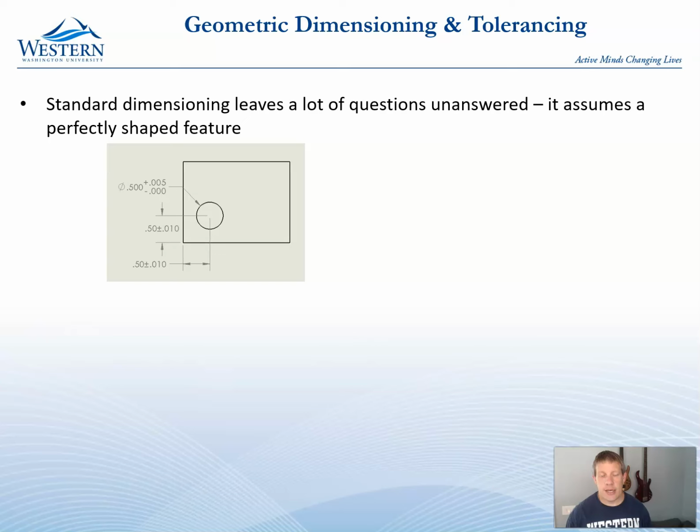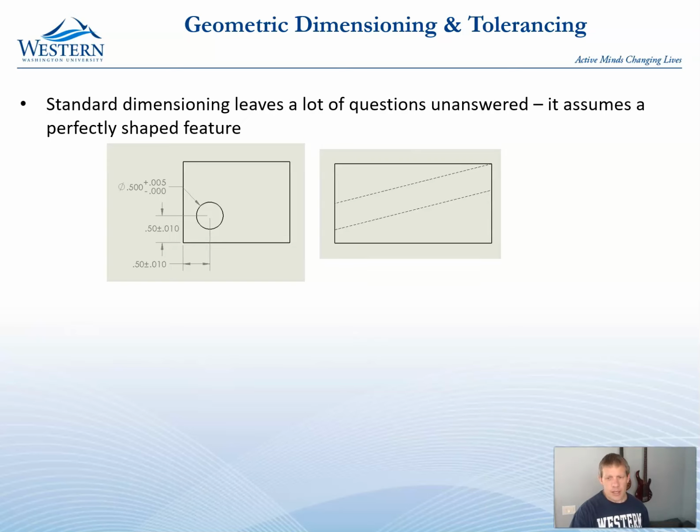Now, the ASME standard says that the positions of that hole as they're called out would be true throughout the entire depth of the hole, but that doesn't mean that this hole is circular. We have 10,000ths on the position in each direction, and so that hole could be, you know, a serpentine back and forth as long as it stays within that range. So it could look like that through the hole. That's of course a drastic amplification of what the errors could be with these small tolerances.